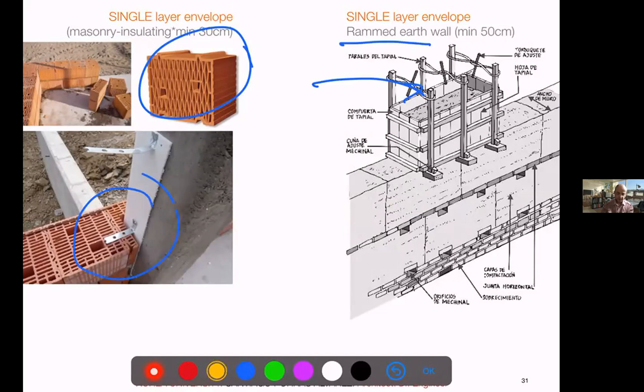See how you have those elements which are structural, right? This is structural. But the columns, the concrete, will help this have more rigidity, right? More stability. There is always a gap, right? Usually masonry and concrete, and steel even less, do not touch. And you have one connection every few meters, which gives stability. So that is a support point, but this is flexible, right?